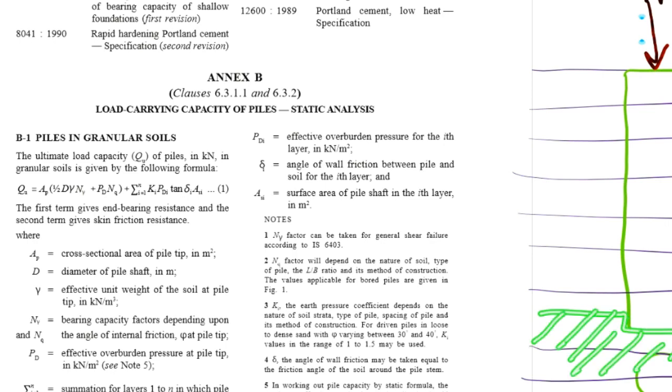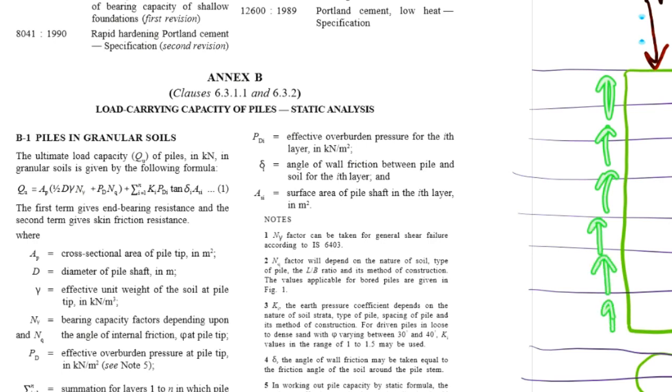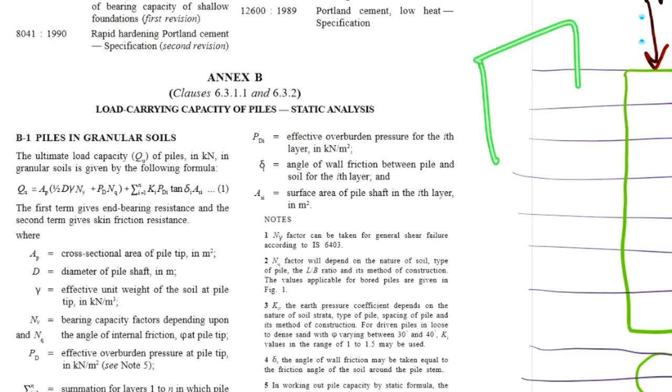But on the other side, when you have friction piles or piles in relatively stiff soils where you have good strata but there is no rock, then the pile load carrying capacity is not governed by its structural capacity. Pile may remain uncracked, but it may fail in vertical settlement. It may have a vertical settlement which is more than the permissible limits. If one of the piles of a group, or under the building you may have say n number of piles, any of the piles settles, then it will create distress in the whole structure. So we don't want our piles to settle by more than generally 12 mm. If it is more than that, then this pile is considered as failure. So we determine the axial load carrying capacity of the pile based on the surrounding soils.